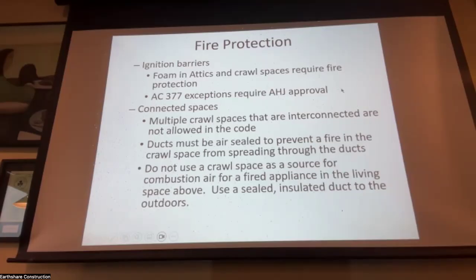So if a foam installer comes to you and says, my product is AC 377 approved, you have to say, send me the literature from the code jurisdiction that approves that use. Because if that building burned down, the code official would be at risk in this case, and they're always trying to protect themselves. So anyway, AC 377 requires code approval.